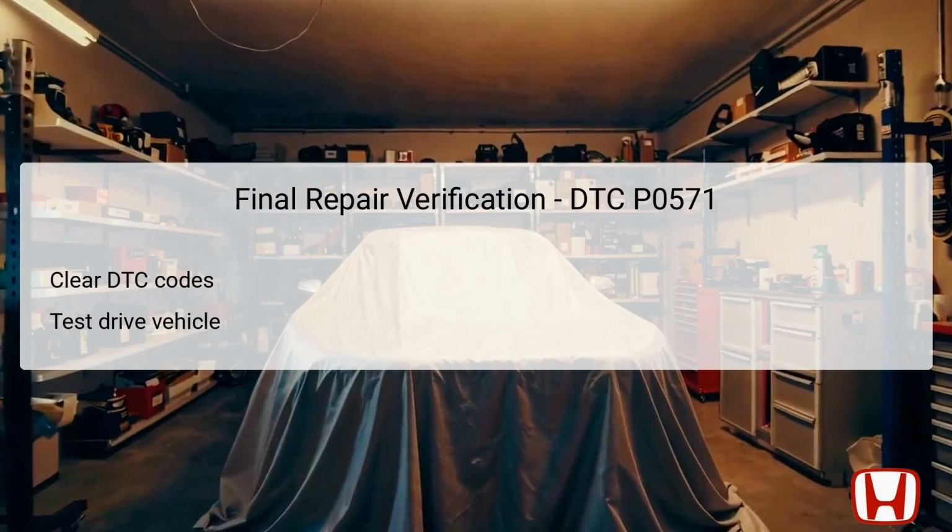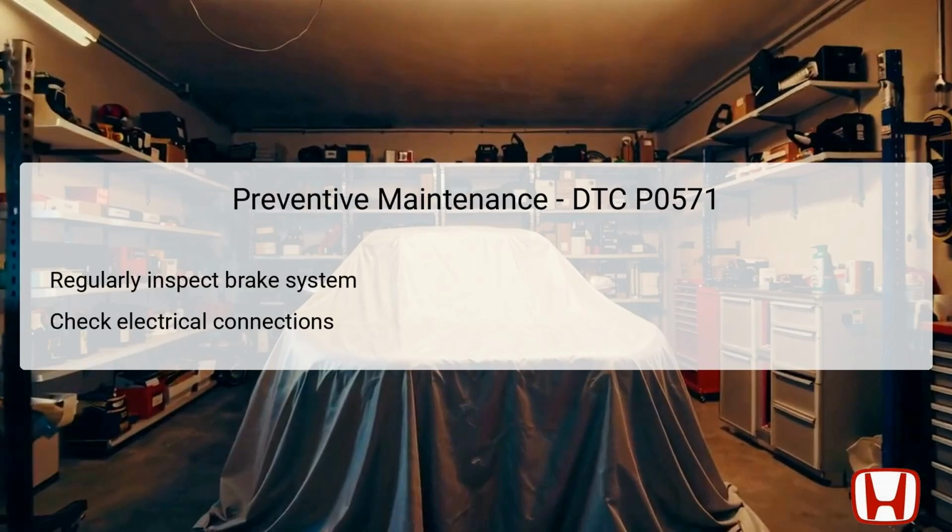Following the clearing of codes, perform a test drive under various conditions to confirm that the brake lights function appropriately and the cruise control operates as intended. A successful outcome during the test drive indicates that the problem has been effectively resolved and the vehicle is safe for operation. To prevent the recurrence of DTC P0571, proactive maintenance is key.